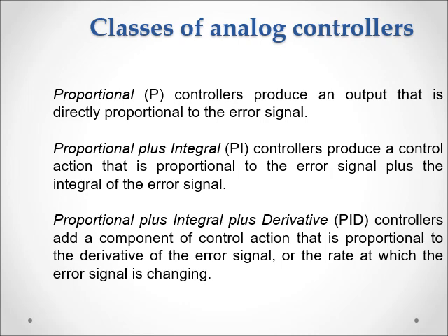If the error is low, actuation effort will also be low. But in an initial understanding, we can feel like, oh, that's good enough. Why do we have to have an I and D controller? There is a reason. The reason is, if you give a very high proportional controller value, then what will be